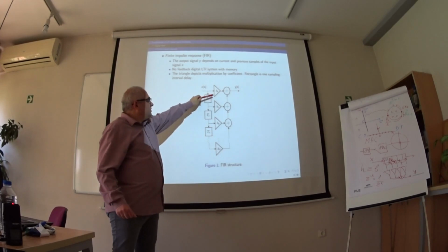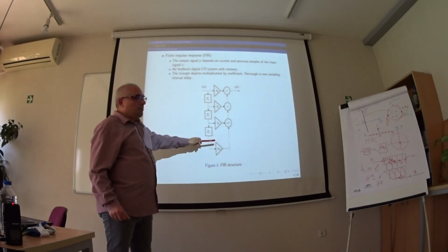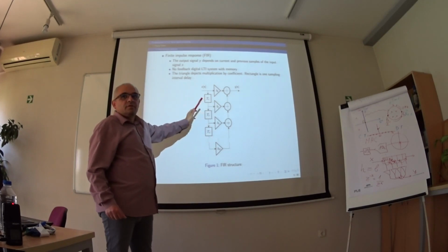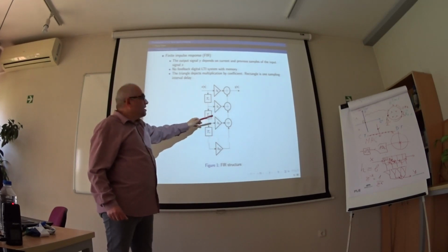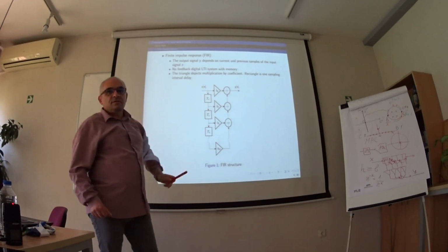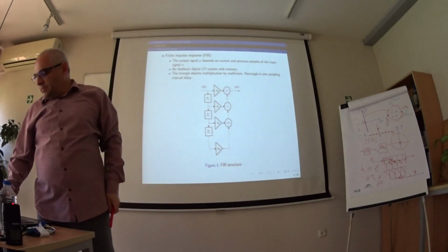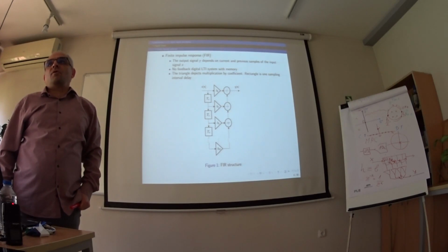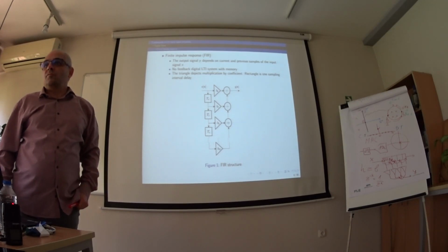The first coefficient is minus the last, and so on. If we have such dependency, symmetry or anti-symmetry, we always have linear phase response and constant group delay.